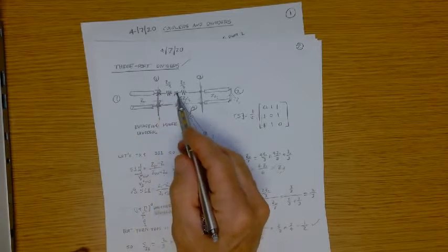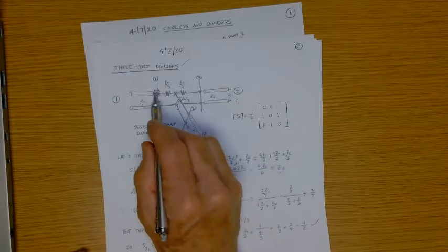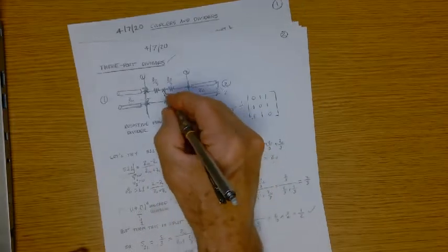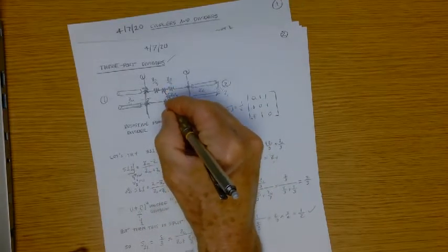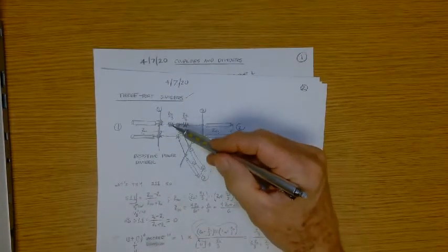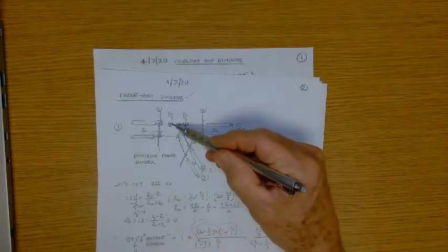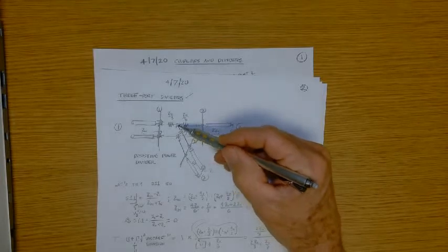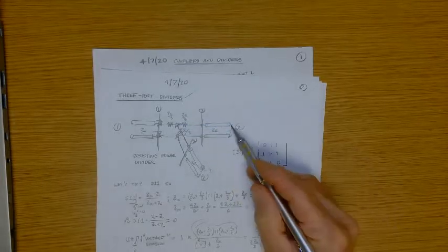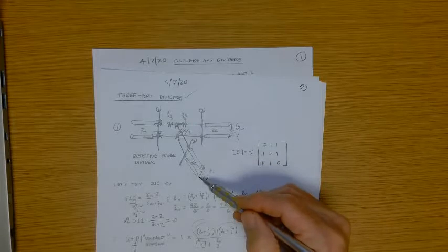And then that voltage, if I want the percentage of that wave that ends up at this pair of terminals, I simply need to do a voltage division between the equivalent impedance here and this impedance. But it's the equivalent impedance here with these two ports terminated, right?